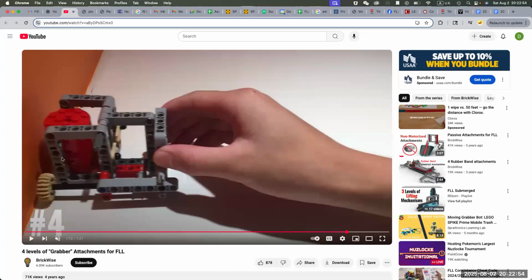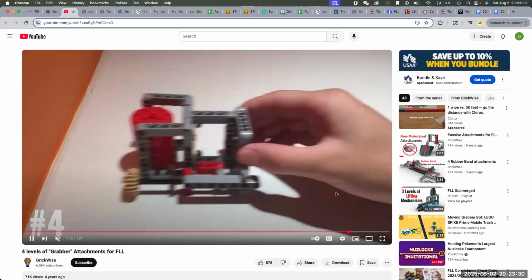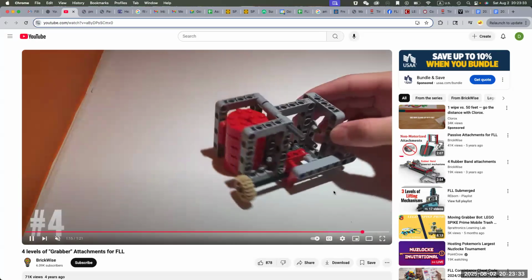This gray piece on the left actually went inside a little bit. So this circle thing, when it touches the wall, actually releases a lock so that this left grabber hand will become smaller, or will move towards the inside. This is how you can clutch the two sides to be able to grab the object firmly.